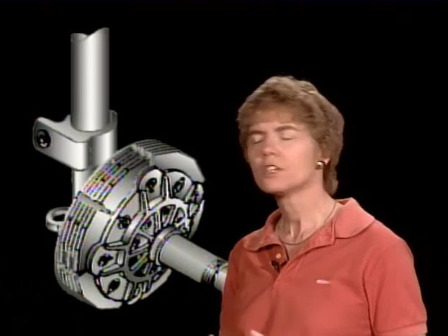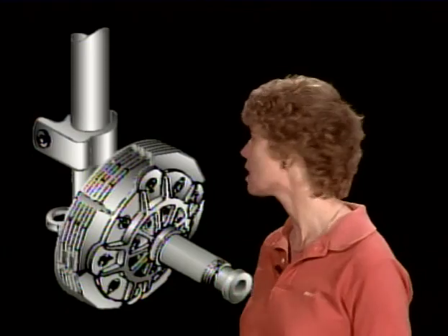The automatic adjuster on a multiple disc brake system, on brake release, traps the correct amount of hydraulic fluid in the brake, and what that does is it gives the correct clearances between the rotating discs and the stationary discs. If that automatic adjuster gets contaminated, it gets particles in it and so on, then you're going to have sluggish and jerky brake operation. So sluggish and jerky brake operation in a multiple disc system like this could be due to a dirty automatic adjuster. Disassemble it and clean it.